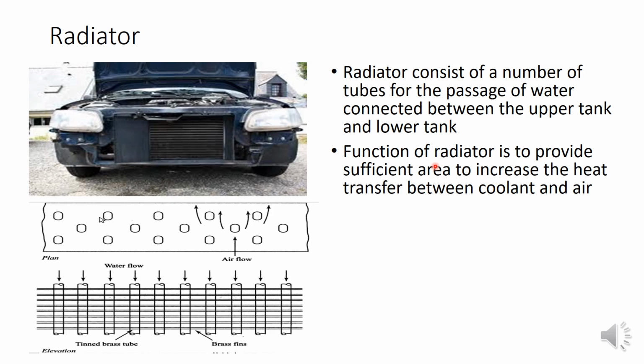We have 3 modes of heat transfer: conduction, convection and radiation. So in the radiator what happens is convection heat transfer, that is, heat is transferred from one fluid to another fluid. So the primary fluid is our coolant or water, which is coming from the engine, hot water, and this becomes cold water by transferring heat to the air.